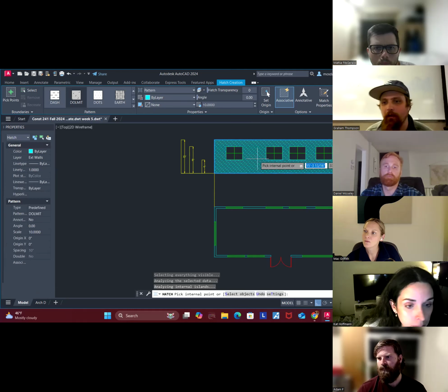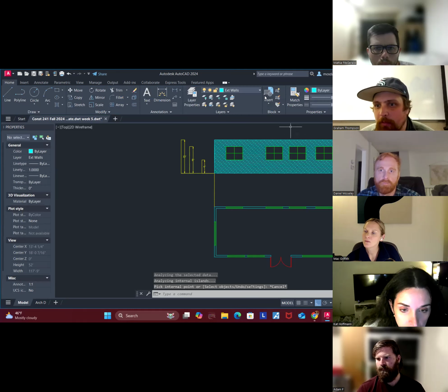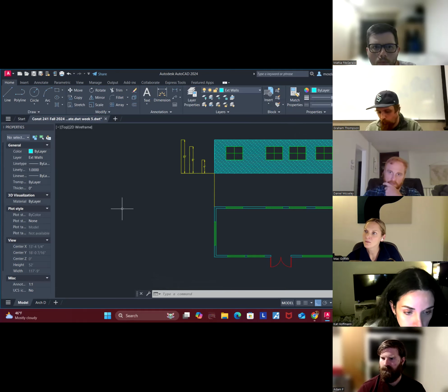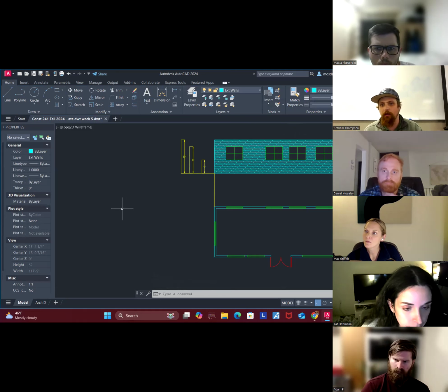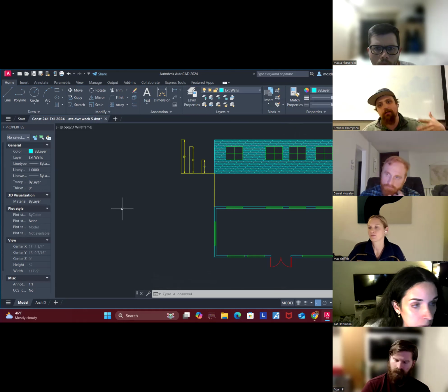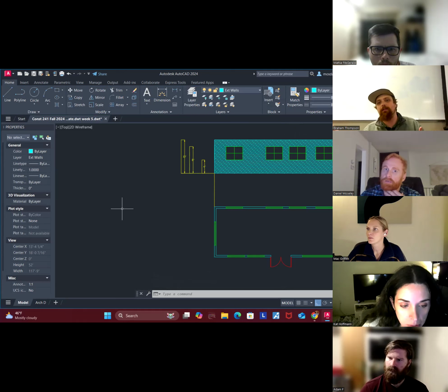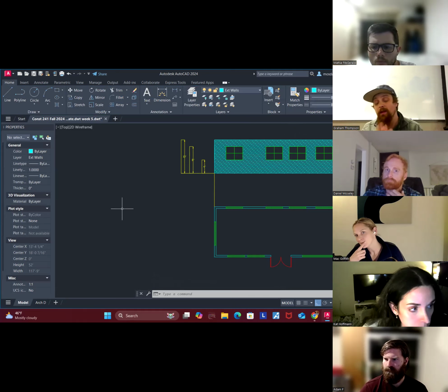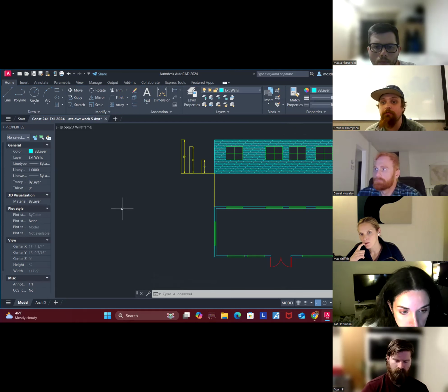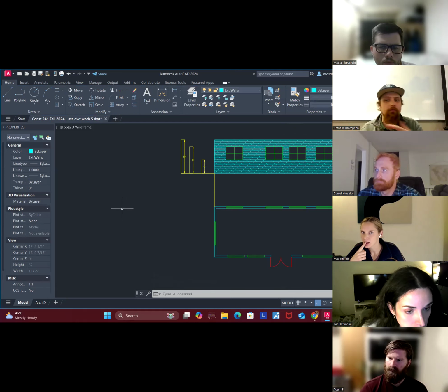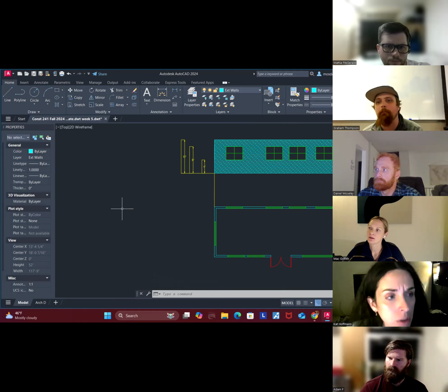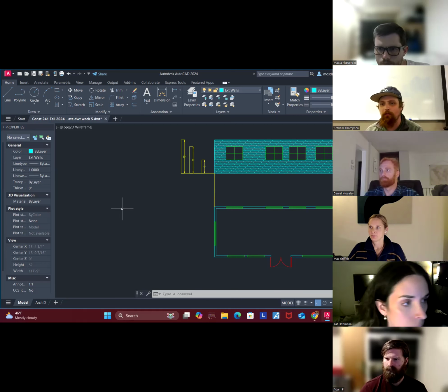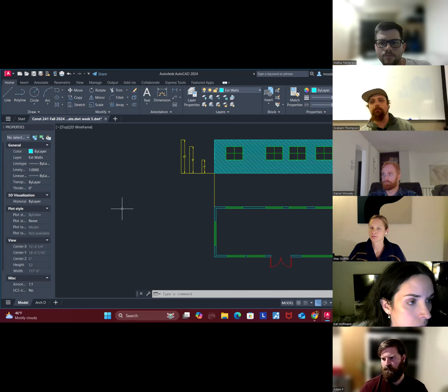So it's all about the scale, and the scale changes depending on the hatch pattern you're using. The hatch pattern may start as a 4-inch by 4-inch brick, but maybe you wanted to represent a CMU block that's 12 inches. You could scale that up by a factor of 3, and now it's 3 times the size. Maybe it's bamboo wood flooring with tiny little slivers. It's all dependent on what you're trying to accomplish, but that scale will get you into the ballpark. We're not trying to be exact. It's just a good visual tool to see what's going on.